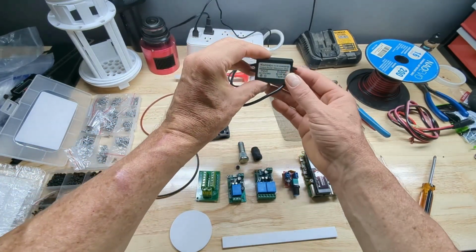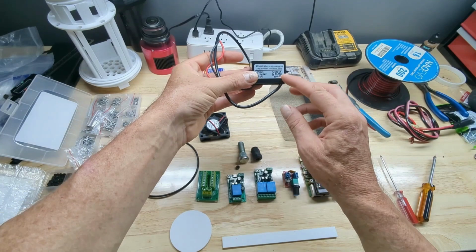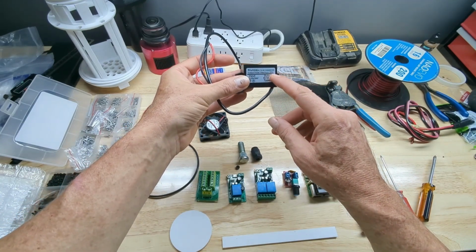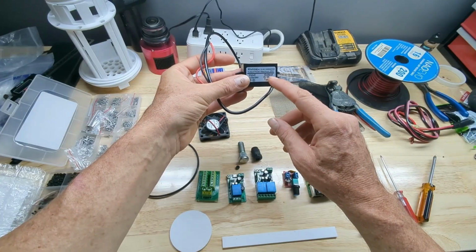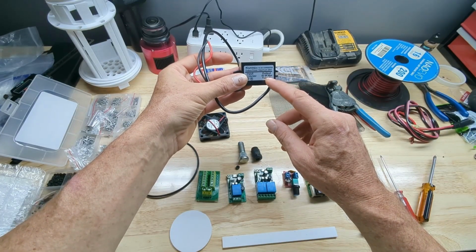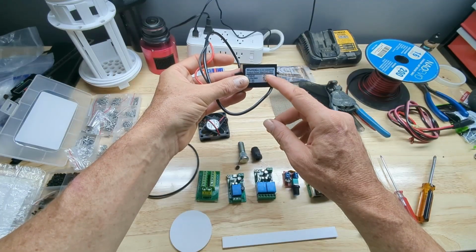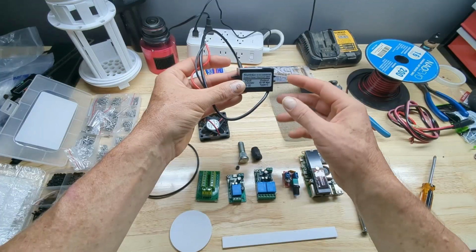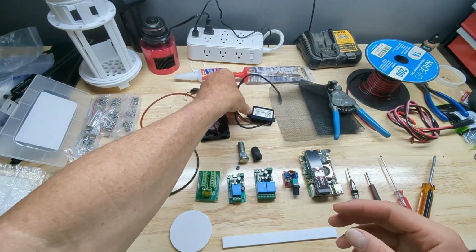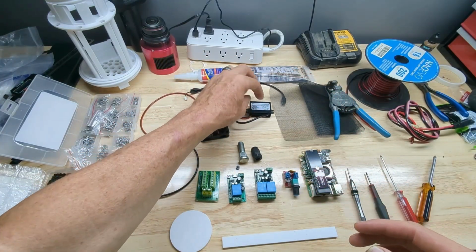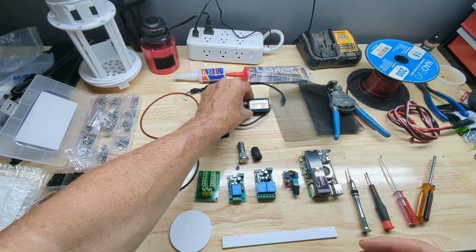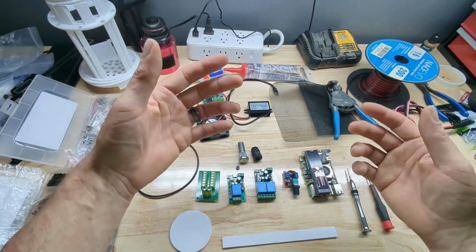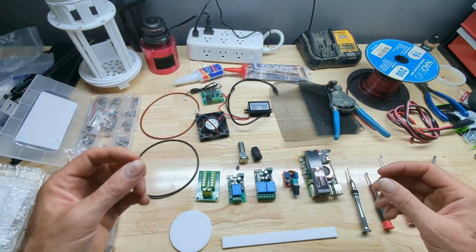This is a buck converter. So this is basically what you're looking for on your Pi power supply. You want to make sure that it can put out at least 25 watts and has a 5 amp output. This is crucial because if you buy a cheaper model, they may only have a 2 or 3 amp output, and it will probably only output 15 watts. If you're using a Pi 5, it'll likely reboot throughout the day and night because it's not being supplied enough power. So you need to make sure that you get the USB power. It's taking 12 volt, converting it down to 5 volt, giving the Pi sufficient power to actually run.